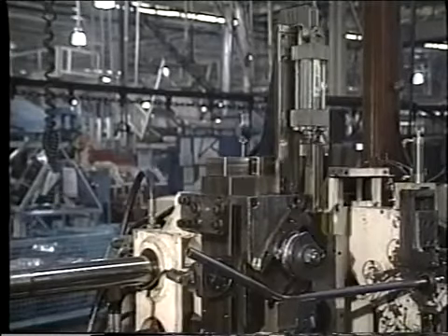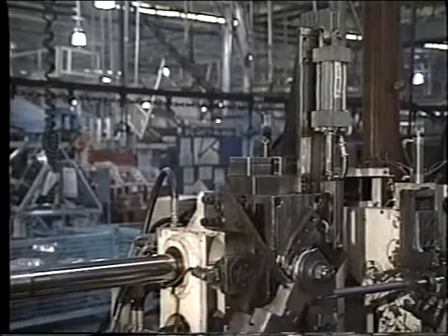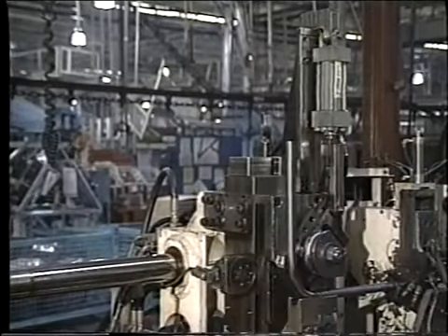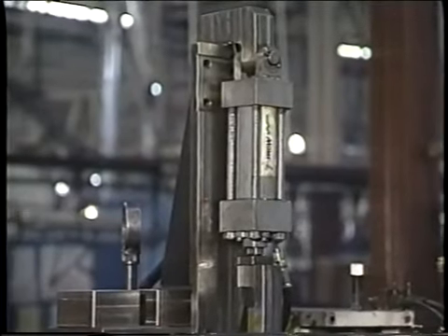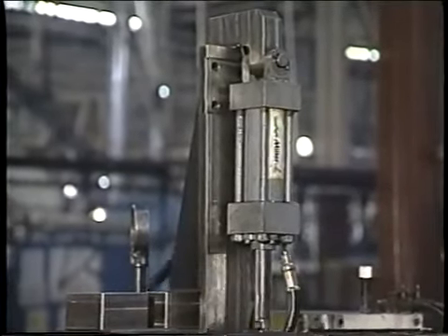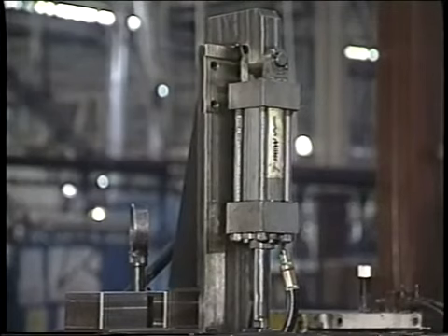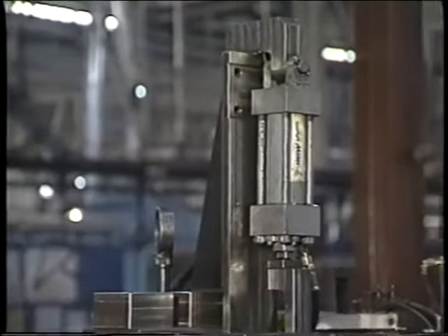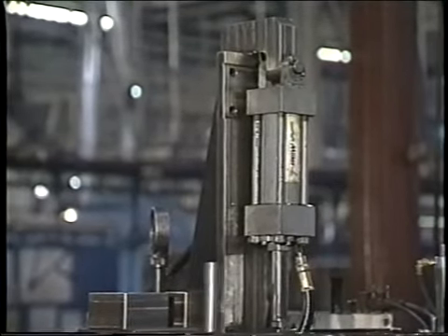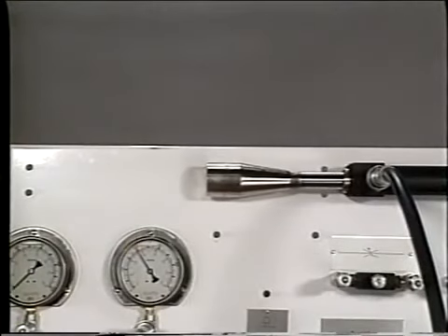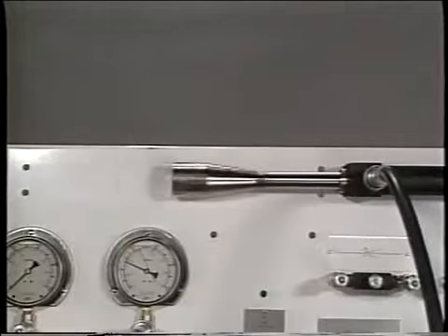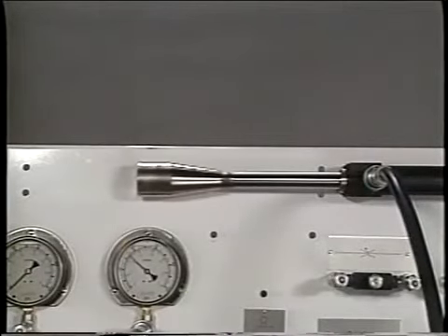In addition to pressure, force, and area, we may also have to know the speed at which a cylinder works. The speed of a cylinder is the velocity at which the piston rod moves. It's usually measured in inches per minute. The speed changes depending on how fast the cylinder fills up with fluid. If it fills up slowly, the rod moves slowly. If it fills up quickly, the rod moves quickly.